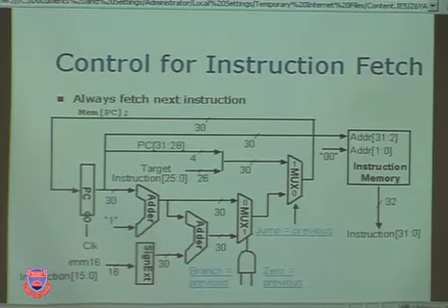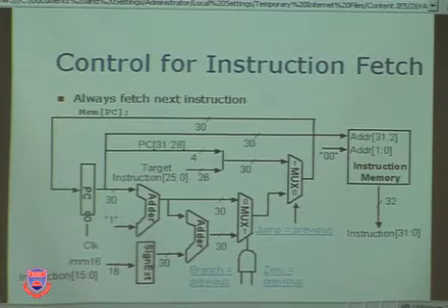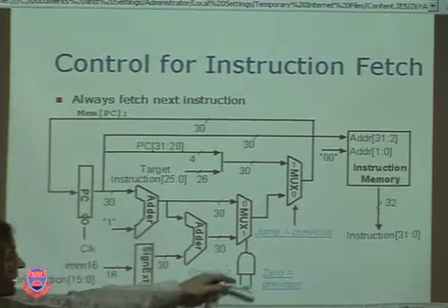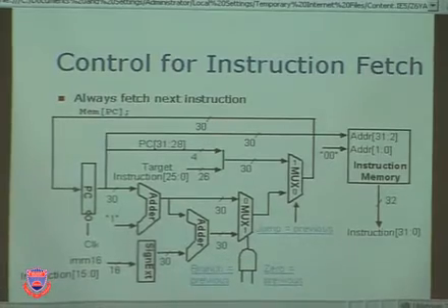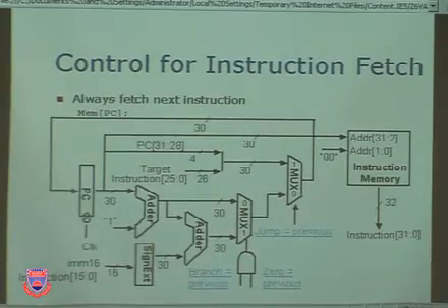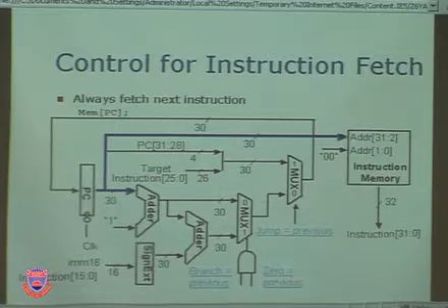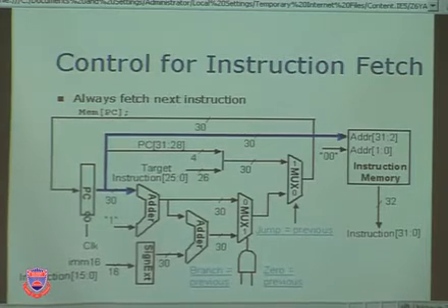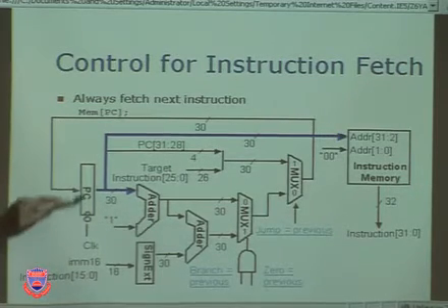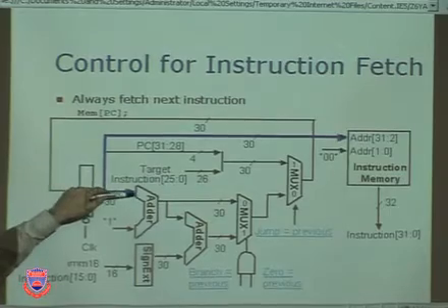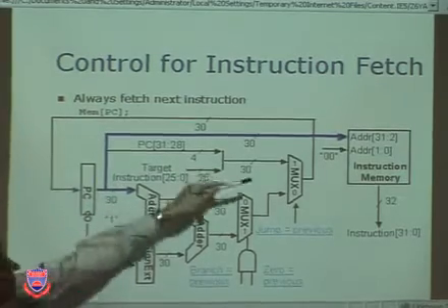And when we want to do an instruction fetch, our branch signal and our 0 signal and our jump signal hold the value of the previous instruction until we change them. Okay, so if we want to fetch the next instruction on fetch, you can see that this value will go here, and this value will go to the memory.